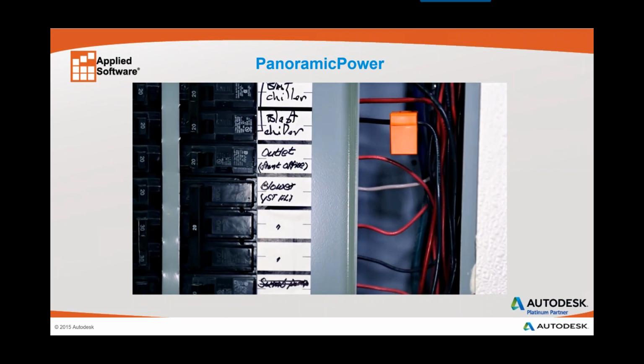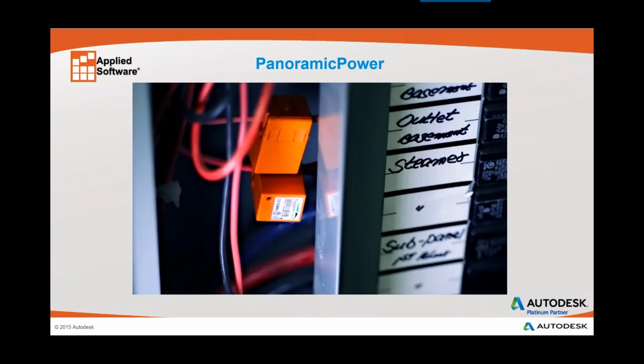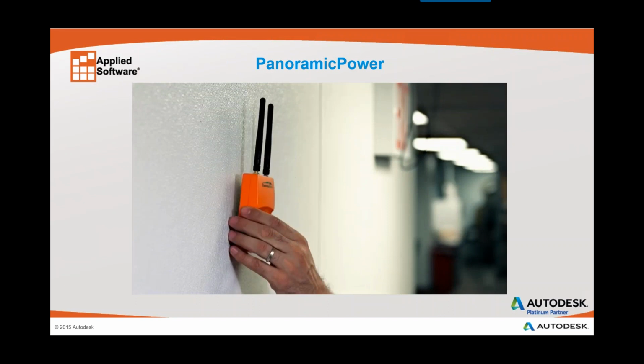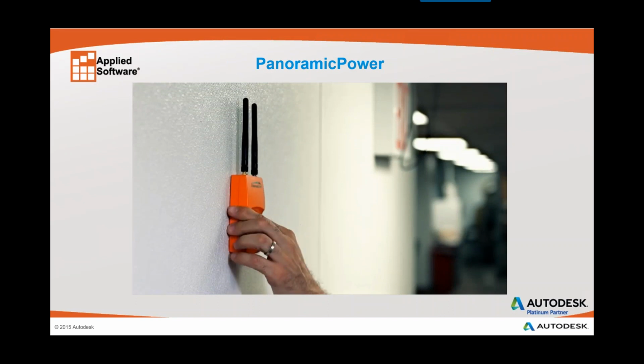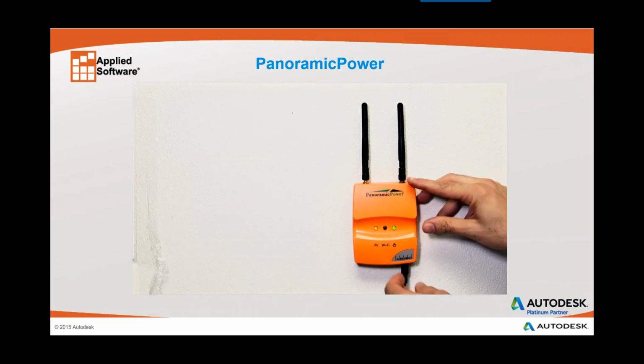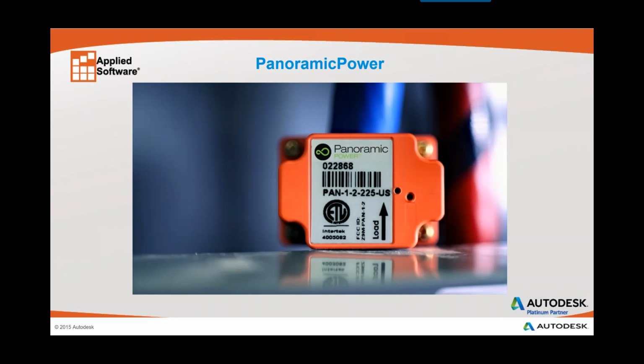Various sensor types are available, for different current ranges and wire sizes, and dozens of sensors can be installed and mapped in less than an hour. The bridge is mounted close to the panel boards and immediately connects to the internet. The bridge communicates the energy data from the sensors every 10 seconds via Ethernet, Wi-Fi, or cellular connectivity. The sensors are self-powered through magnetic fields that surround the wire, and they never require maintenance, service, or battery replacement.